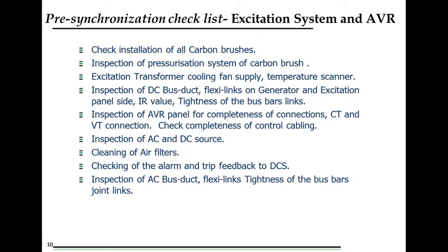Now there will be a few pre-synchronizing checklists of the excitation system. We must check that all the carbon brushes are properly installed. All the carbon brushes must be properly pressurized to the ring so that there is no sparking when the generator comes into operation.